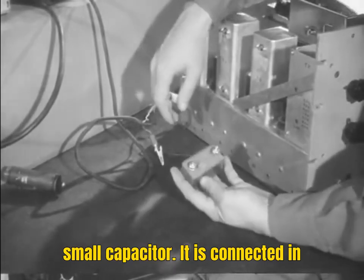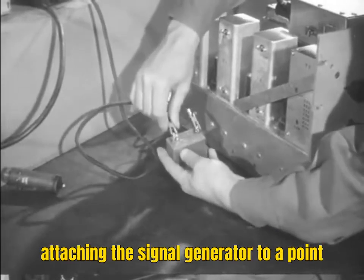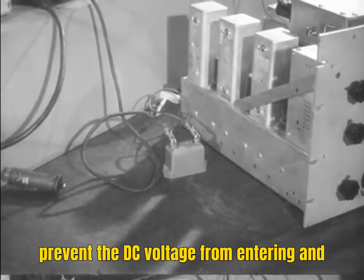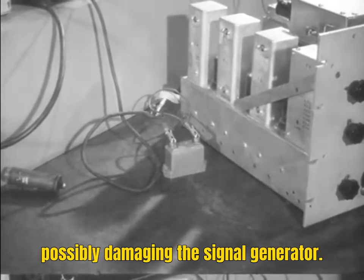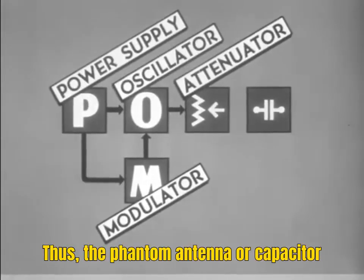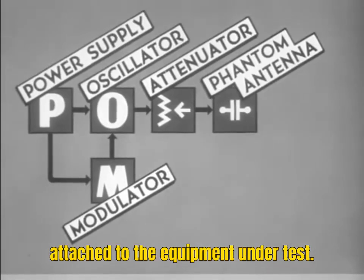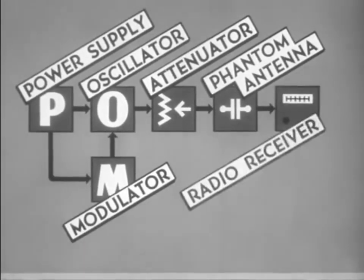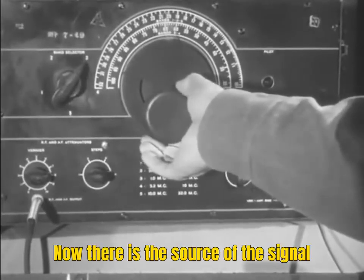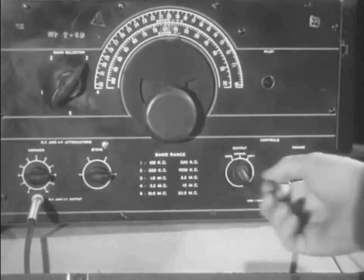It is connected in series with the signal generator. A capacitor must always be used when attaching the signal generator to a point where DC voltage is present. This will prevent the DC voltage from entering and possibly damaging the signal generator. Thus, the phantom antenna, or capacitor, takes its place in the system and is attached to the equipment under test. Now there is the source of the signal established and the set to receive it.